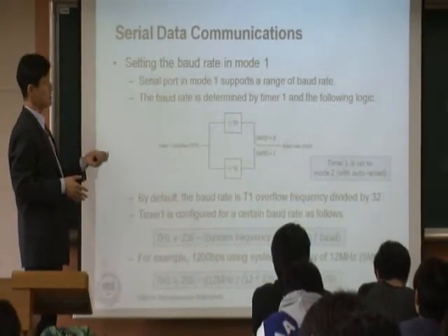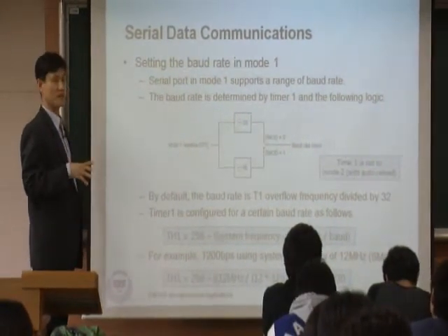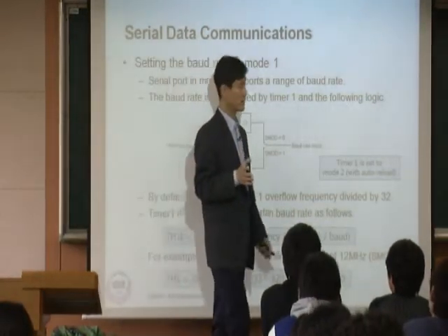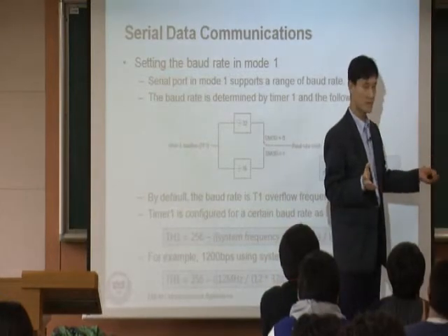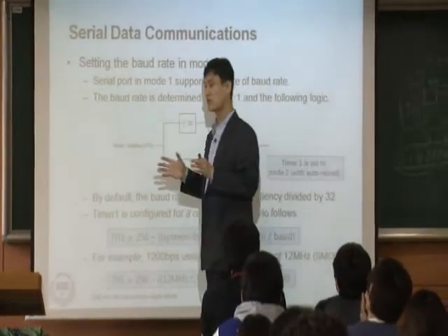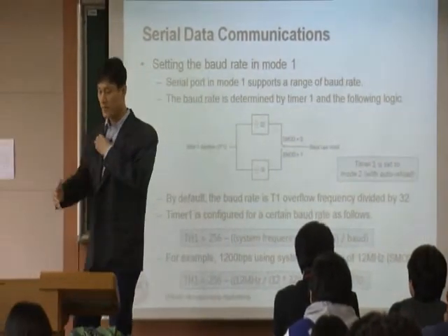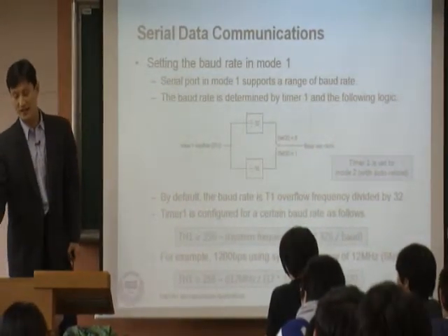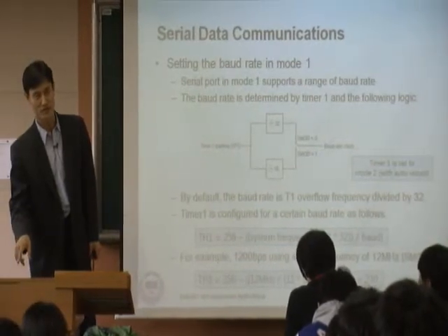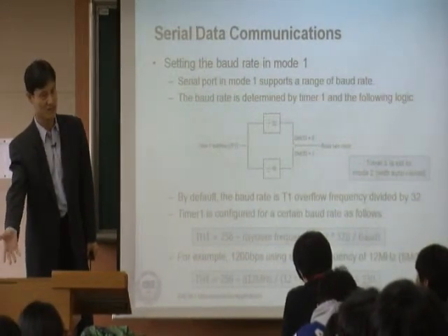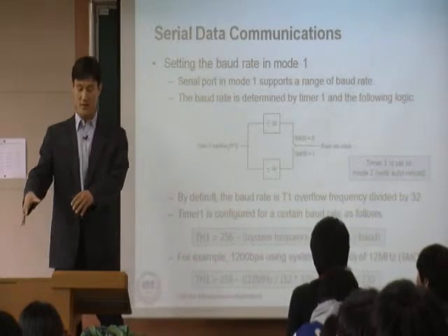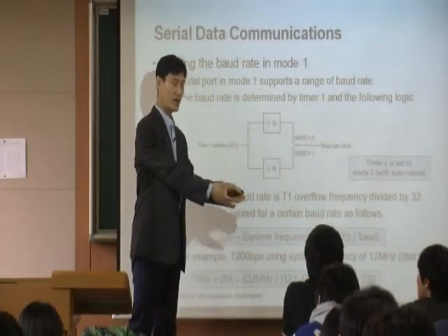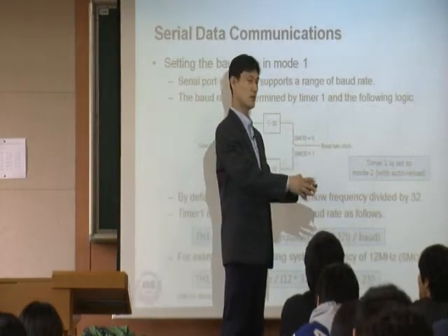This slide shows you how to set the baud rate. It is very important to set the baud rate because of this problem. On the PC side, as I showed you, I can open HyperTerminal and set it by clicking the menu. However, your PC is connected with our 8051 board, and how do you set the baud rate in your board?